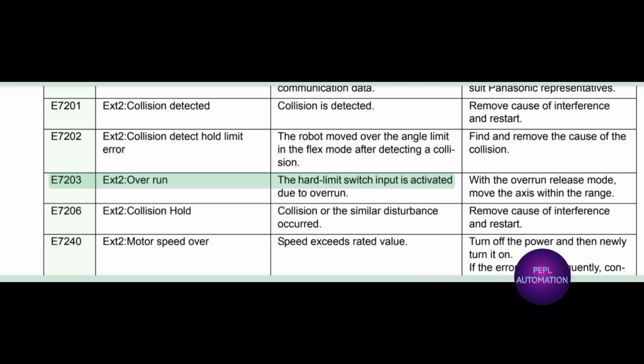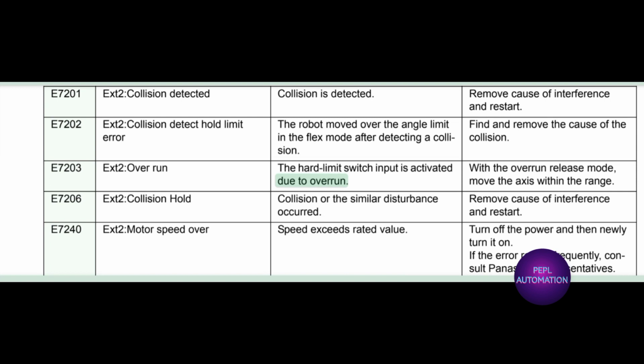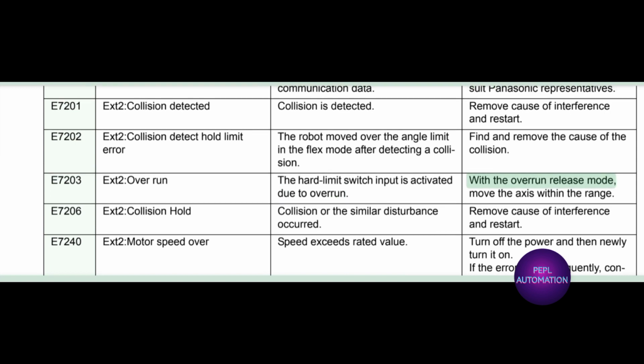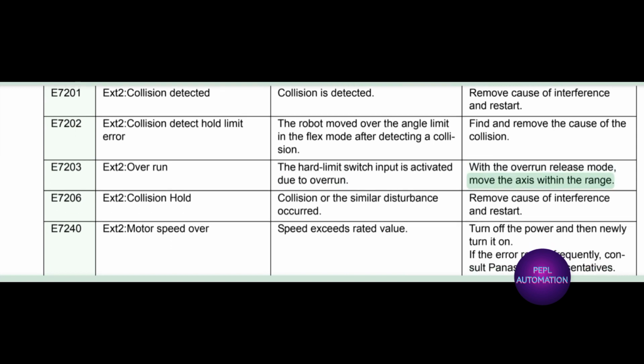E7203X2, overrun. The hard limit switch input is activated due to overrun. With the overrun release mode, move the axis within the range.